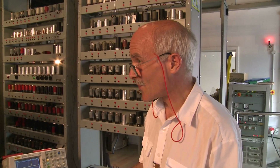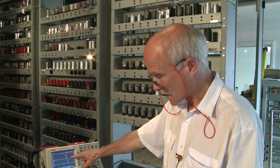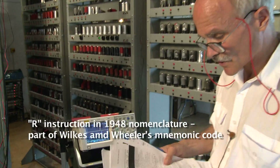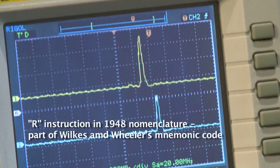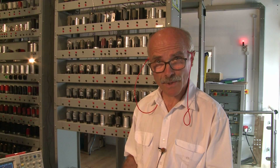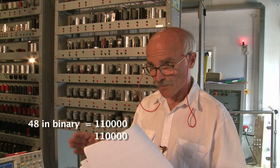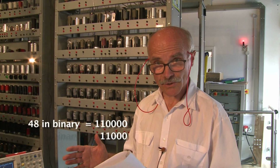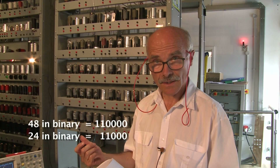Okay, if you could set all down except F15 up. So now we see the order set with just bit number 15 set on, and that corresponds to the R instruction, which is the right shift instruction. The right shift instruction is very important because it's a very simple means by which binary computers can divide a number by 2. Simply by moving all the bits to the right, you divide the whole number by 2, and we can perform that very fast using electronics entirely.